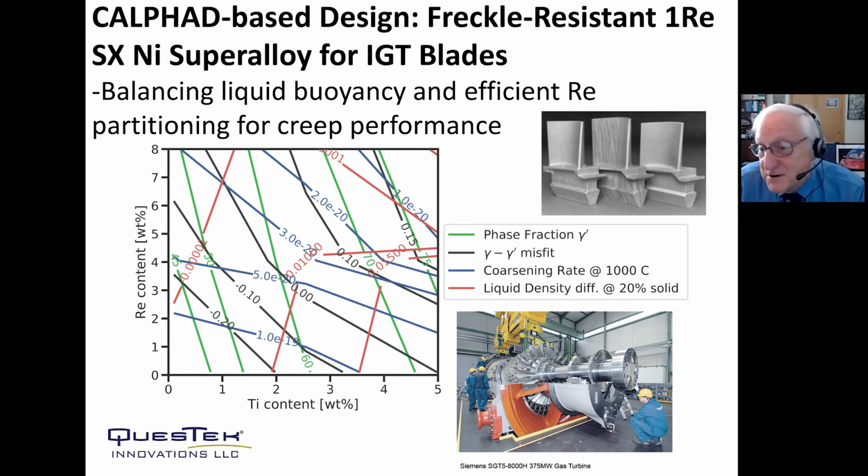So back in the US, we love our shale and want to keep fracking it. And so the opportunity for us is natural gas. A problem that was called to our attention by Howmet in the late 90s is the incompatibility of the highest performance aeroturbine blade alloys with the scale of industrial gas turbines, that the rhenium-bearing alloys cannot be produced at larger scales because of a thermosolute convective instability during solidification that causes freckle defects.